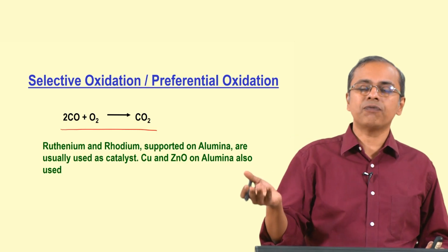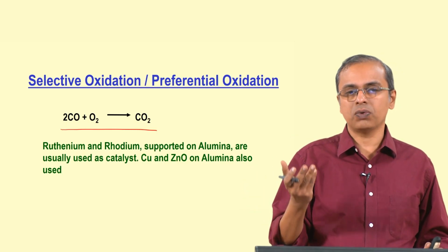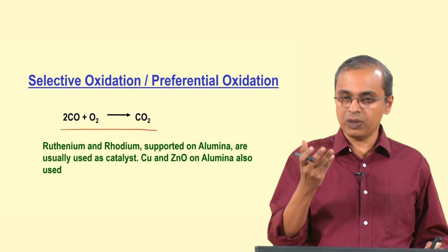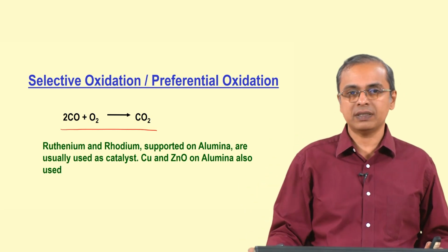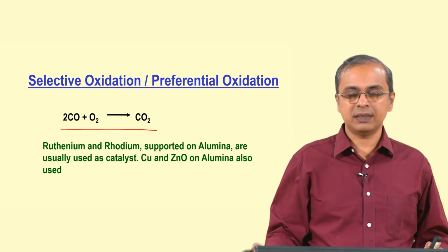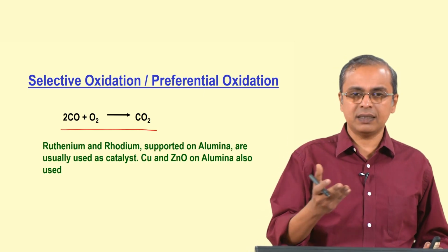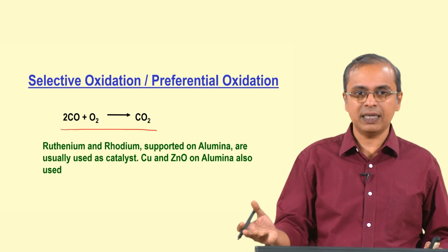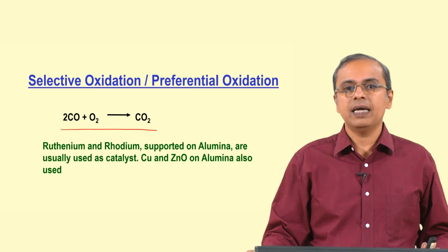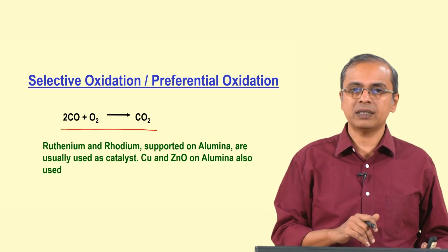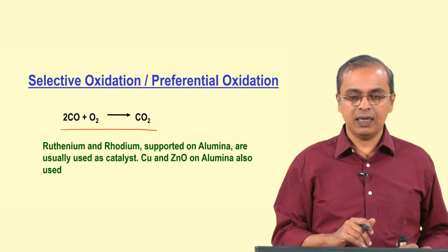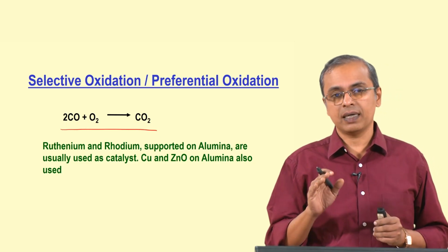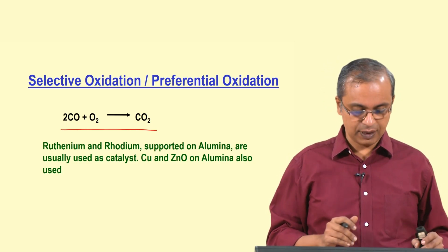So, you are going to waste some fuel also in this process. It is not going to be that you will only remove the CO, you are going to waste some fuel, some hydrogen is going to get wasted in this process, and so you have to look at this a little bit carefully. But it is necessary in some ways because you have to really get the CO off the system, and so we do have this selective oxidation or partial oxidation, preferential oxidation so to speak, being done to take care of this activity.